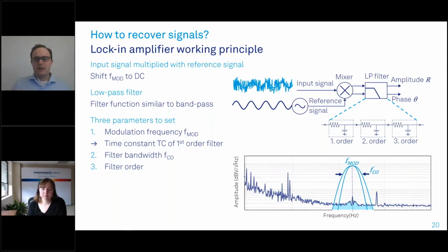The benefit is there. If you have, for example, a noisy laser, both your inputs would go up and down in the same way, and you would not see that as a signal, because only the difference between those input signals matters. Now, this helps you to get rid, for example, of a really huge offset, which you have if you only detect a very strong laser beam on a photodiode.